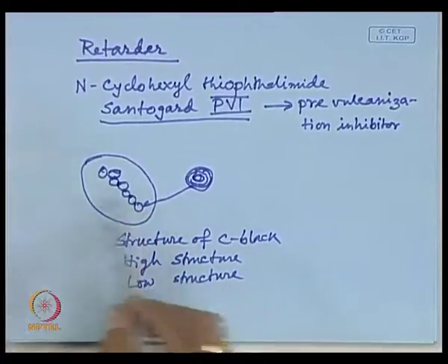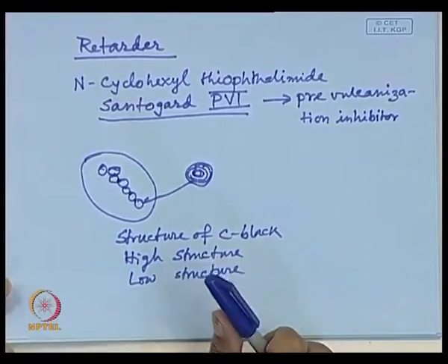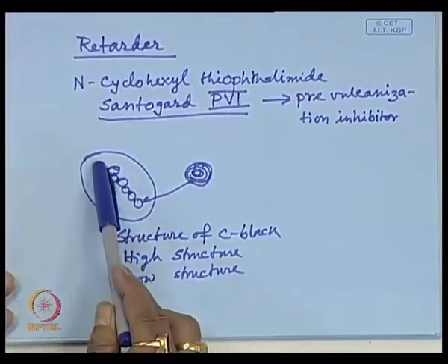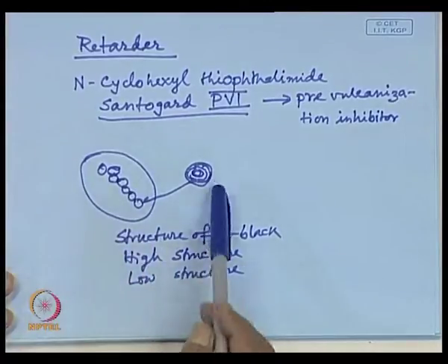Now, again, they dictate the processing characteristics of a rubber compound while carbon black is used as a filler, for incorporation and dispersion. It has been found, it has been experimentally verified, that high structure carbon black is difficult to incorporate in rubber compound, but it is easy to disperse. Please note it down. Once it is incorporated with difficulty, then the latter part of dispersion becomes easy. High structure means that by virtue of their bigger volume it is difficult to incorporate in rubber, but they are easy to disperse, because carbon blacks have a property of agglomeration by virtue of their surface forces, surface energy.